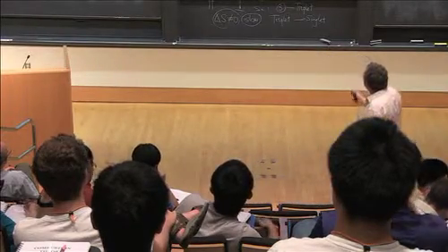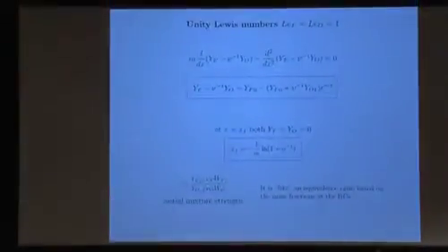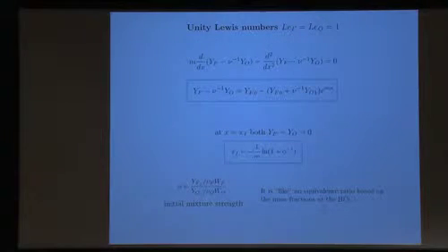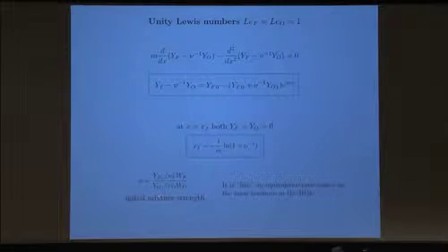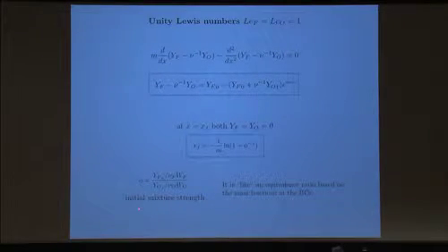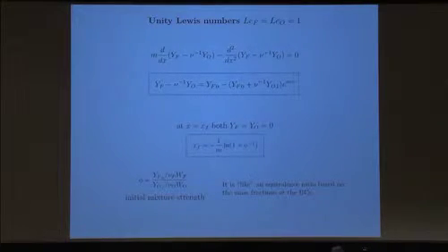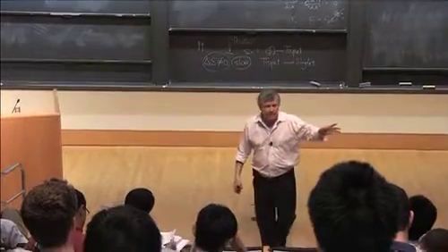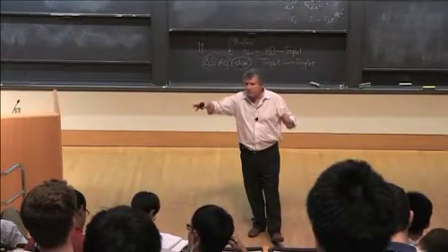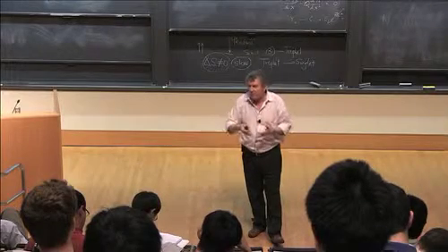But what I have referred to as phi here is the ratio of the mass of fuel in one end to the mass of oxidizer in the other end. And I like this notation, or this term, better than equivalence ratio, which is somewhat confusing, and I will call it an initial mixture strength. So that's the initial mixture strength. In other words, it's what you provide at the relevant boundaries relative to stoichiometry, okay? If phi is equal to 1, it means that the fuel on the fuel boundary and the oxidizer at the oxidizer boundary were supplied exactly at stoichiometric condition.